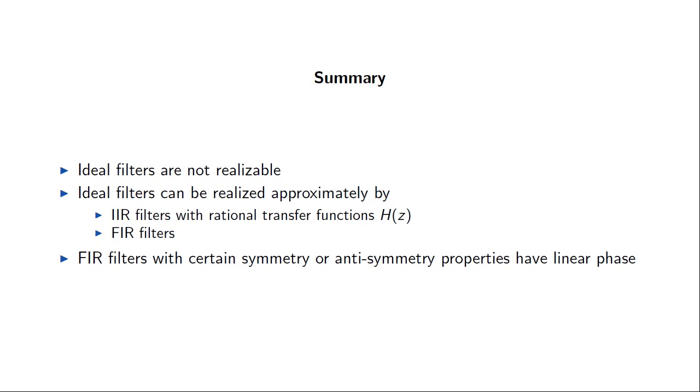So linear phase is a property that is sometimes very important and sometimes not. If you're working, for instance, with an audio application, it turns out that we are relatively insensitive to phase differences when we listen to a signal. However, if we view a signal, as in the case of an image, we're extremely sensitive to changes in the phase. So for applications like image processing, having a linear phase is absolutely crucial. And then it's good to know that we can satisfy this property in FIR filter designs.